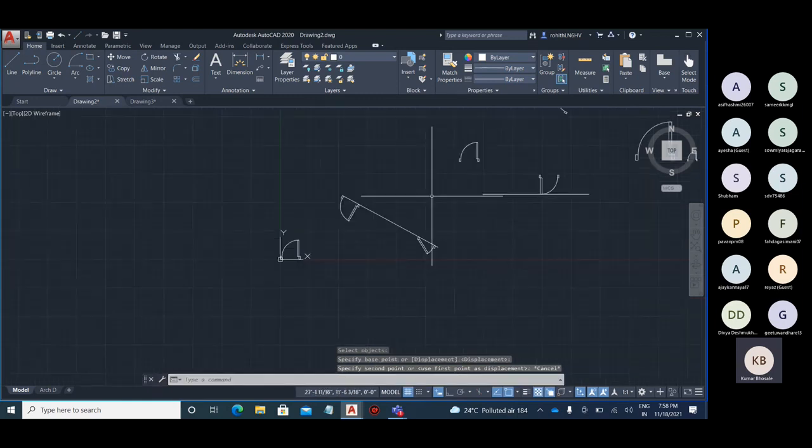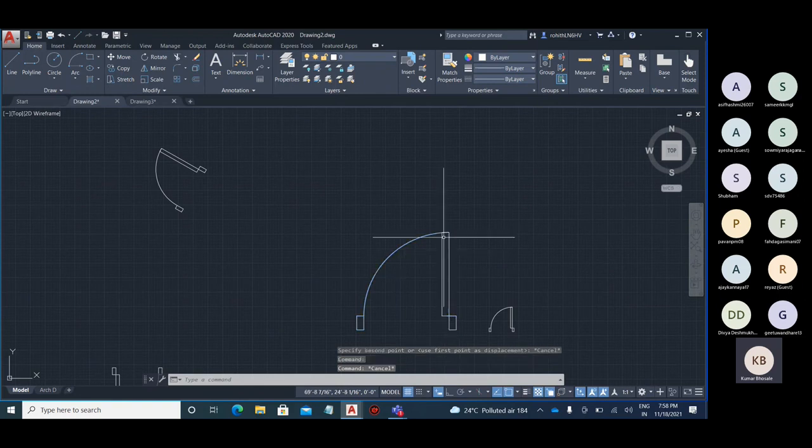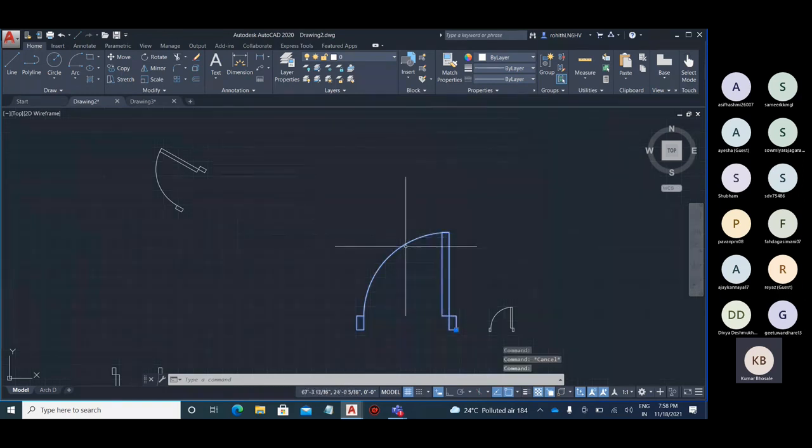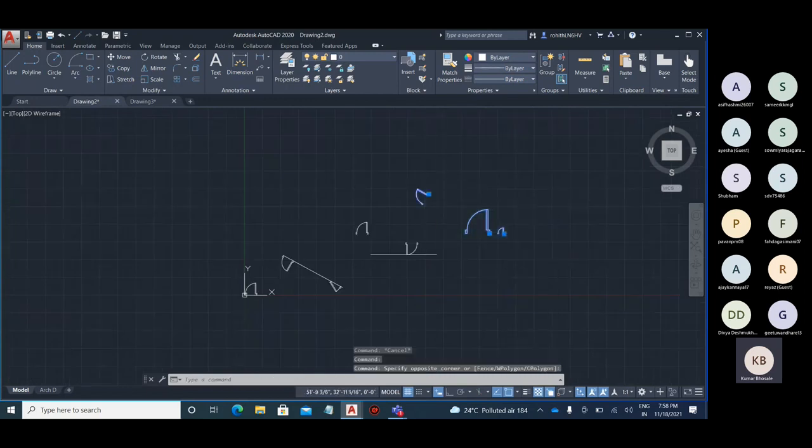But in blocks, completely all the things are being selected, so this is a complete single unit. If I make a selection, the complete block is selected. That is why it cannot change with the stretch command. So you can use the scale command for that.